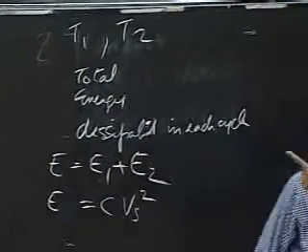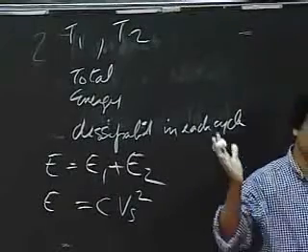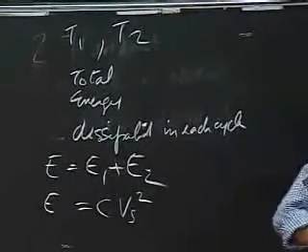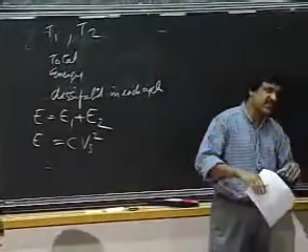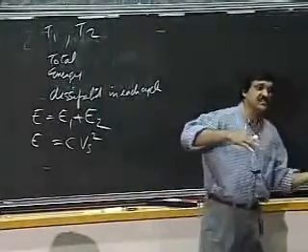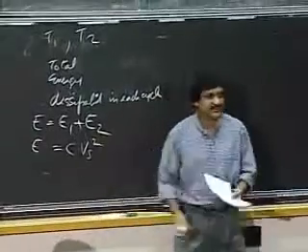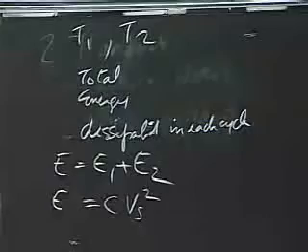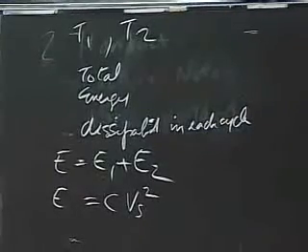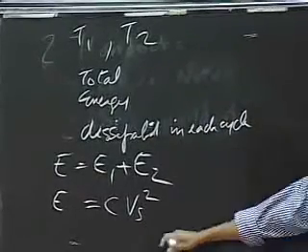So if I have an arrangement of switches and capacitors like that, I charge the capacitor, discharge the capacitor, charge the capacitor, discharge the capacitor. What it's saying is that in a charge-discharge cycle, I'm using up CVs squared of energy: half CVs squared when I charge it up, and half CVs squared when I discharge it. That's what I get.